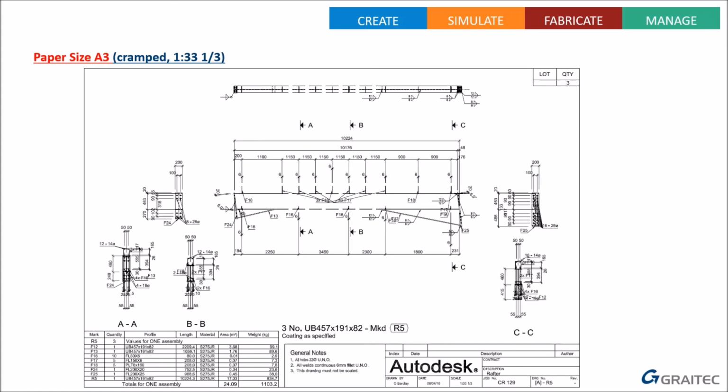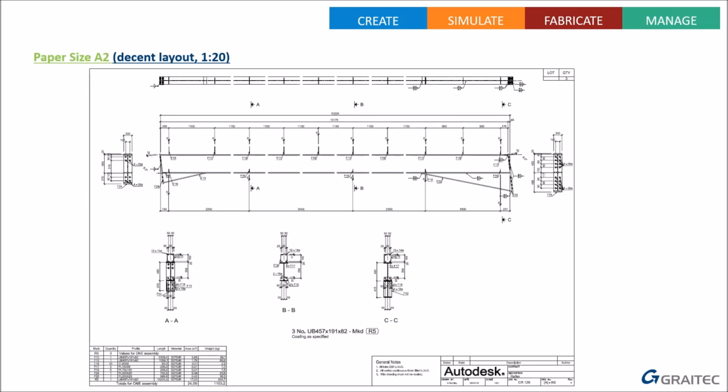It's not very tidy, not very neat, but if I let that use an A2 sheet, it's got a lot more breathing space, got the same number of dimensions, the text size is exactly the same. It's at 1 to 20 now on an A2 sheet, much clearer and easier to read, much nicer layout, and you can still shrink it down. I can still read that on the screen. The screen hasn't changed size, so the text has been scaled down.